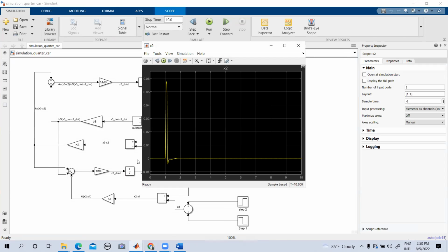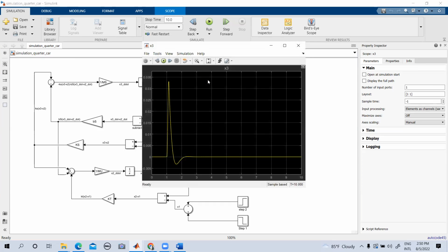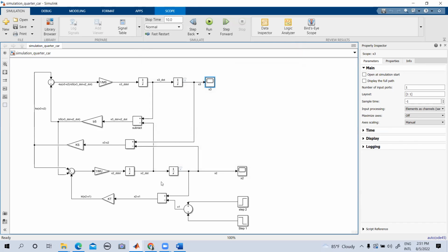There's a high peak suddenly, like an impulse, and it settles. The displacement goes to a high peak and settles. So you can observe the response of the overall system. There's a high overshoot, then an undershoot, and then it settles. The settling duration is close to 2 seconds, which is not that bad, but you can try to optimize the system by changing certain values.